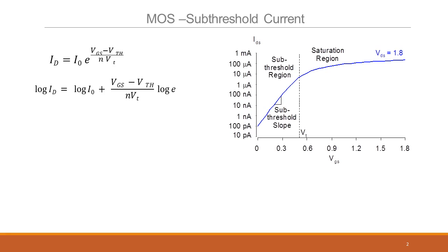It is actually not saturating. It's not the MOS characteristics we drew before, where ID versus VDS, the current tended to saturate. This is saturating only because we've drawn it on a log scale. Ideally, this is an ever-increasing current going as a square of VGS minus VTH. We've seen that before. Just because it is drawn on the log scale, it looks as if it is saturating. Don't get misled by that. All we are focused on here is this linear curve.